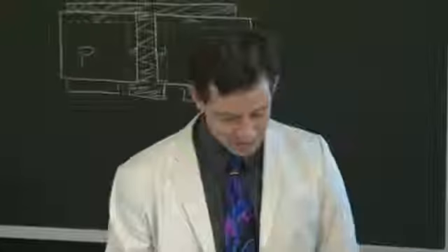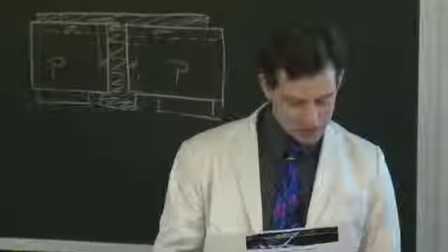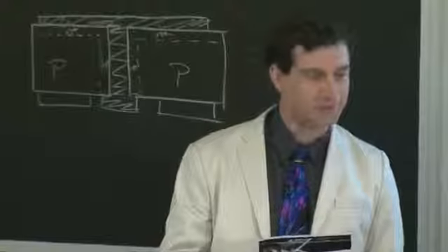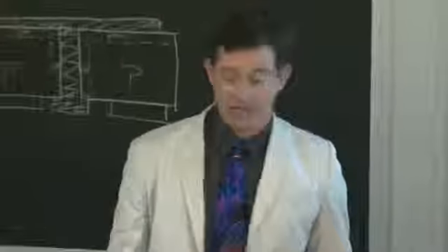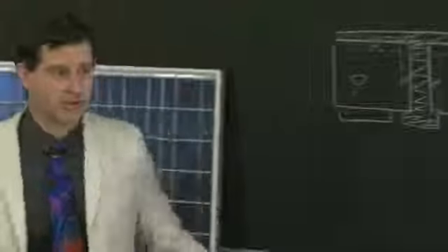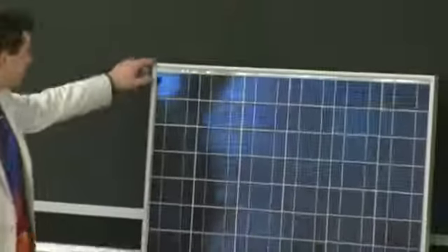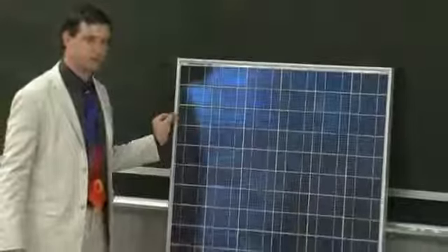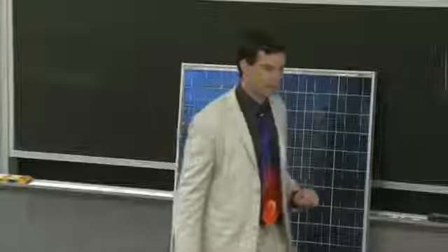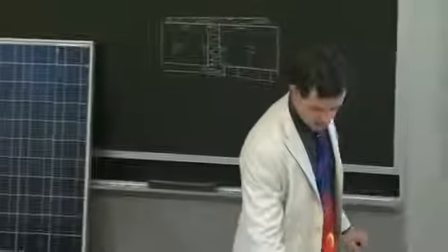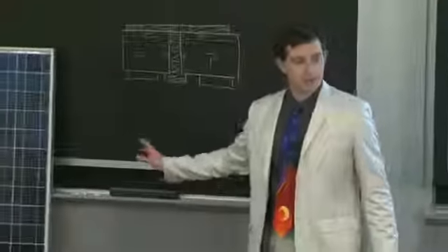Is there a reason why they don't put efficiency on the sheet? Well, you could probably very easily calculate the efficiency, right? There are two types of module efficiencies. There is what's called total area efficiency, where you take the total area of your module all the way up to the aluminum frame and calculate that as your area. So you take your maximum power, rated at AM 1.5 sun conditions, and divide it by the area.